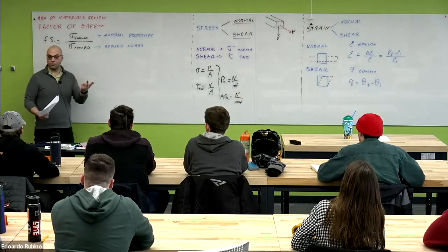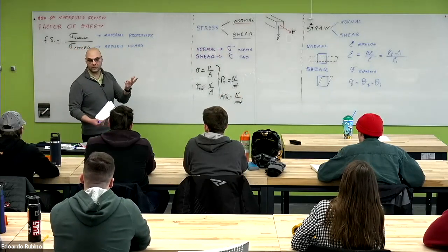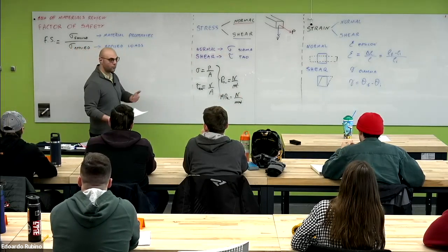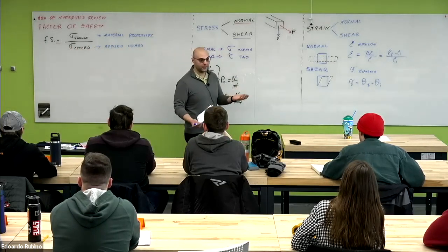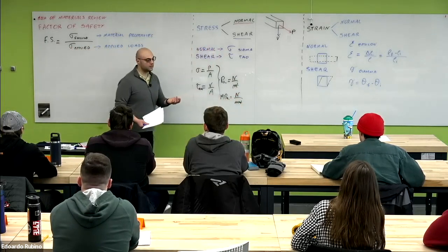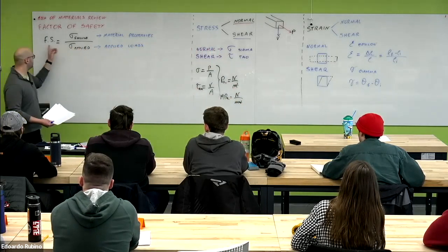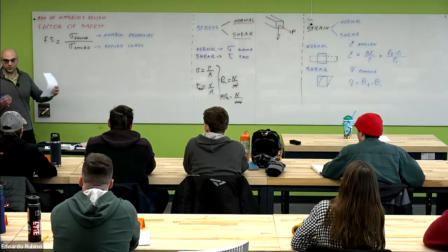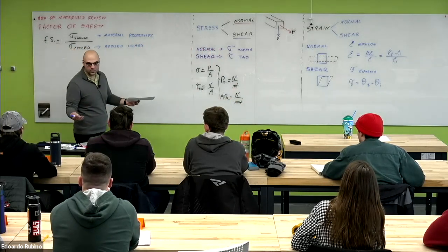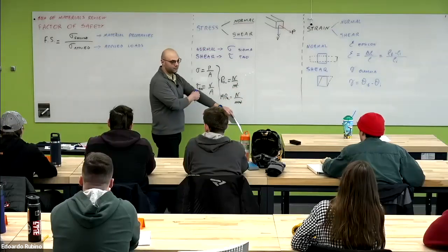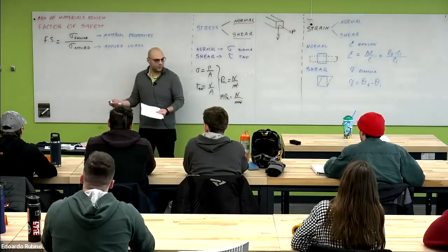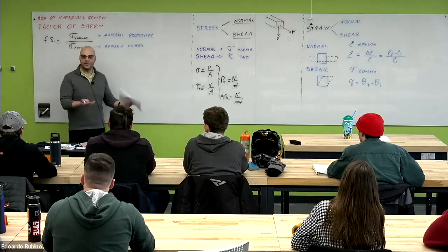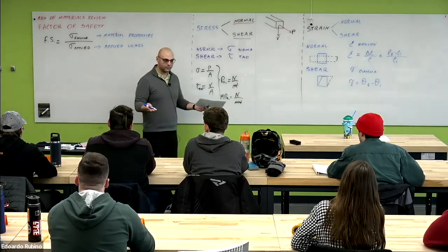These three are very important aspects that we have to consider, because, for example, if you think about an aircraft, weight is a very important parameter. So we as engineers need to make sure that we have a certain factor of safety, but we cannot make our structures as big as we want, because when we increase the factor of safety, it means that we increase the size of our structure. We increase the size, we increase the weight, and then the aircraft will not take off anymore.